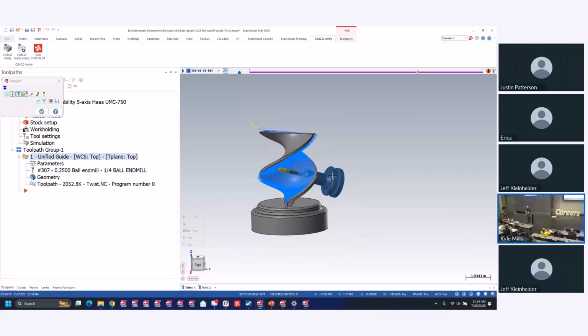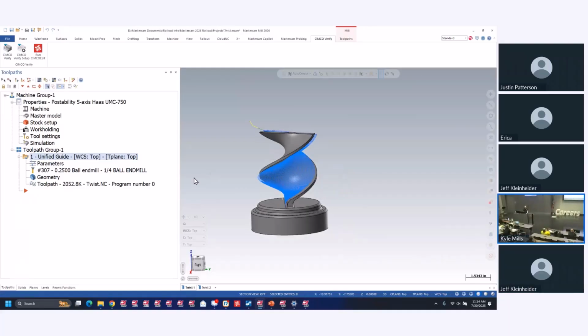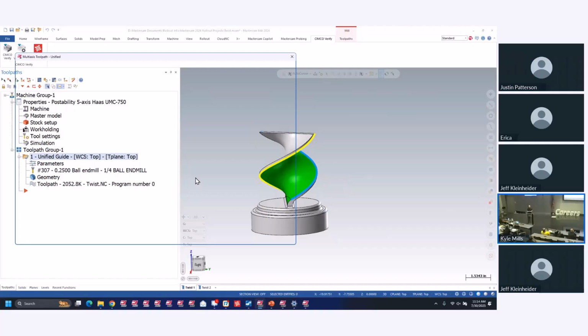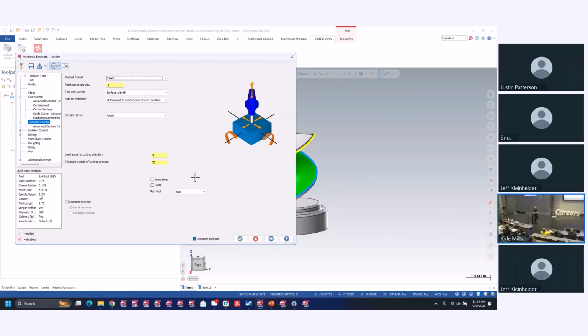So what I really like to do, and I do this all the time with 5-axis machines, is I turn it to a 4th-axis operation. Because in a 4th-axis operation, you can actually control where your C-axis or your B or A axis are as that 5th axis. So whatever you're spinning around, in this case, if we're spinning around the C, we can lock our B over to a certain location. I do it all the time. Eliminate as much motion as you can. And not only that, it'll make your part way more concentric. You're just spinning around the C and kind of dancing up in X and Z there. So let's go ahead and do that.